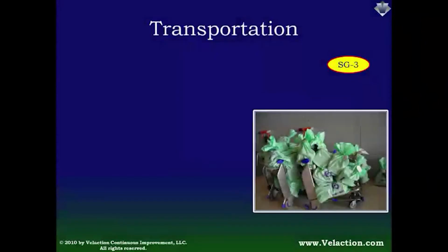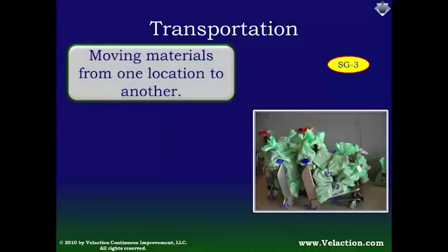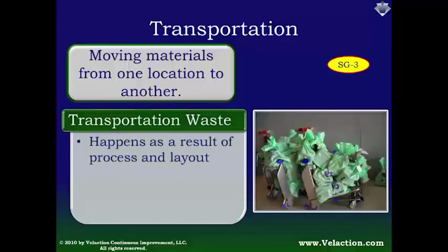The next waste is transportation. Anytime a material or good or file or document is moved from one location to another, you are observing a waste of transportation. Transportation waste is a direct result of a poor process or layout.